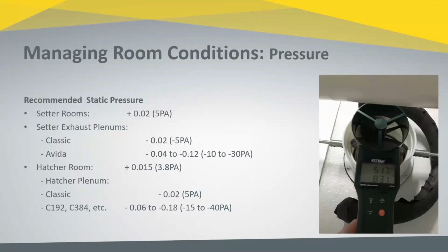And oftentimes when we look at hatcher machines, we forget that it's critical to use an anemometer to measure air being exhausted out of the machines to verify that you have adequate airflow for the machine.